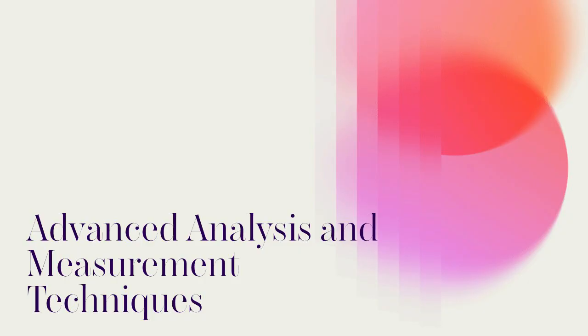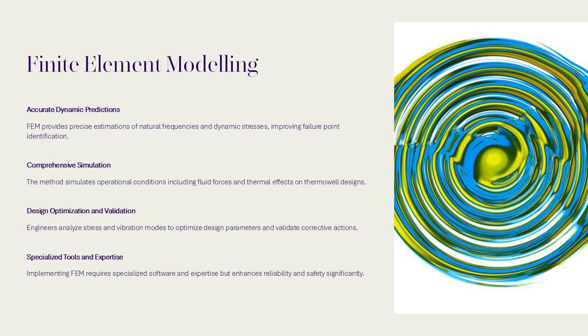Finite element modeling, dynamic strain and vibration measurements. Finite element modeling, FEM, offers a sophisticated approach to predicting thermowell behavior under dynamic conditions. Unlike simplified calculations, FEM provides accurate estimations of natural frequencies and dynamic stress levels, enabling engineers to identify potential failure points before they occur. This method involves creating a detailed computational model of the thermowell and simulating operational conditions, including fluid forces and thermal effects.